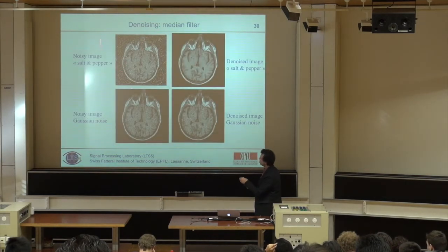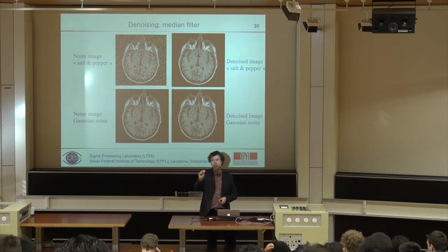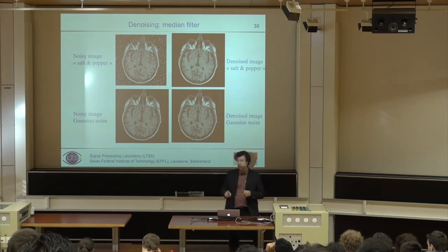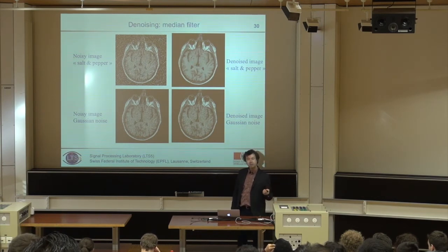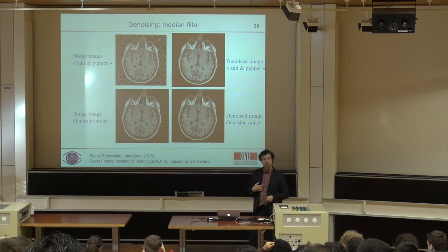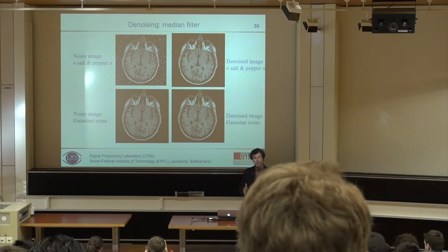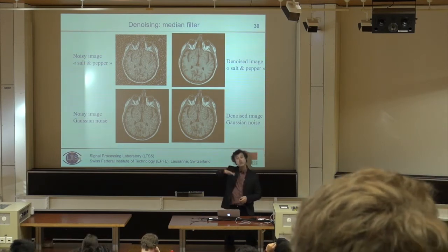If I take that extremely noisy image, with a lot of little points, each of which is obviously an exception considering its neighborhood, replacing each pixel by the median of its neighbors gives you that image. So you see how powerful this median filter is to remove what is called salt and pepper noise, that you can get when you have an electronic noise, for instance. This is really the result of that. There is no smoothing of the edges. The edges remain sharp because they are a strong transition between one region and another.